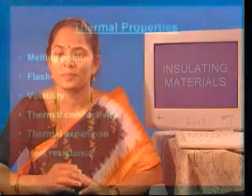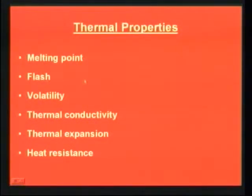The thermal properties of insulating materials: the insulating materials must be stable within the allowed temperatures. Certain materials like waxes, plastics, bitumen compounds and resins are softened at low temperatures. This may cause deterioration of mechanical properties and the insulation may melt out of the coil windings, causing internal short circuits. Some of the thermal properties are melting point, flash point, volatility, thermal conductivity, thermal expansion and heat resistance.